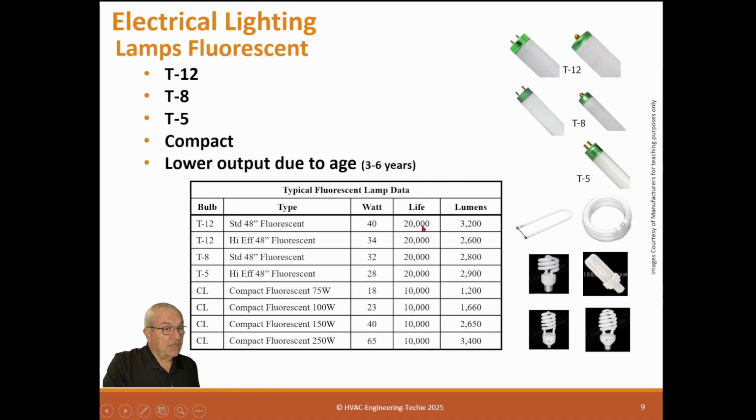And unfortunately, most people didn't have operations protocols in their facility to change the bulbs every 5 years. That's what I recommended. You have an ongoing program that every 5 years you change the light bulbs in a space to new fluorescents, so you can get over and start over. If you just let them be replaced as they burn out, they'll still get replaced in 6 or 7 years, but the quality of the lighting in the space will be much, much lower.